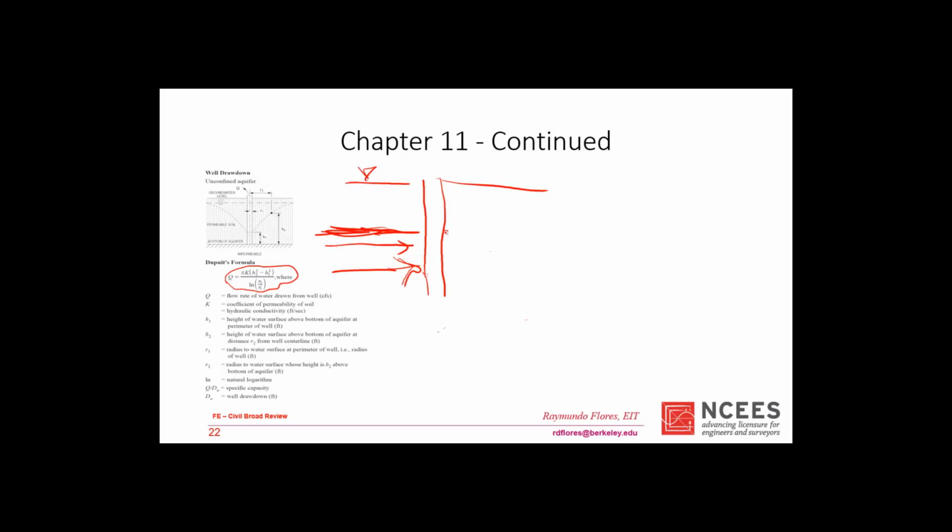So remember, for the confined thing, we have a solid here, right? This is confined. In the confined case, you only have flow going here, but here's the kicker, is that you still have an elevation head that's changing. So maybe some water might go through here and here, but in the confined case, we're assuming that the flow is completely in this location and that it's mostly not here. So as you get away from this point, you have changing elevation heads.